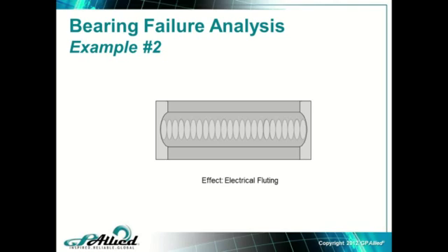Right? So in ultrasound, this would make a very pretty sound because it would be very even, very symmetrical. It wouldn't sound like your typical spalling in a bearing fault, which has a very random, very rough sound. In ultrasound, this had a beautiful sound to it. I wish we had a recording of it, but we didn't. But the problem was the ground wire on the motor had corroded away, and most people didn't think anything of it because they're like, oh, it's grounded through the electrical system. It's not a big deal. In actuality, it's a very big deal.